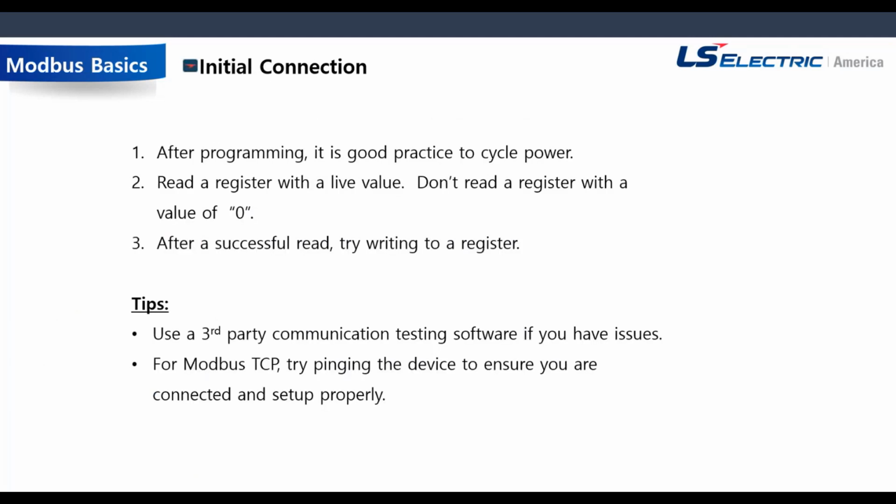All right, so after you're done with your programming, it's a good practice to cycle power. I've done this before where I set up a bunch of network comm stuff and I don't cycle power, and I spend 2 hours trying to get things to work, and all I really need to do is cycle power and it works right away. So after you do any initial setup for programming, especially related to communications, it's good practice to cycle power.